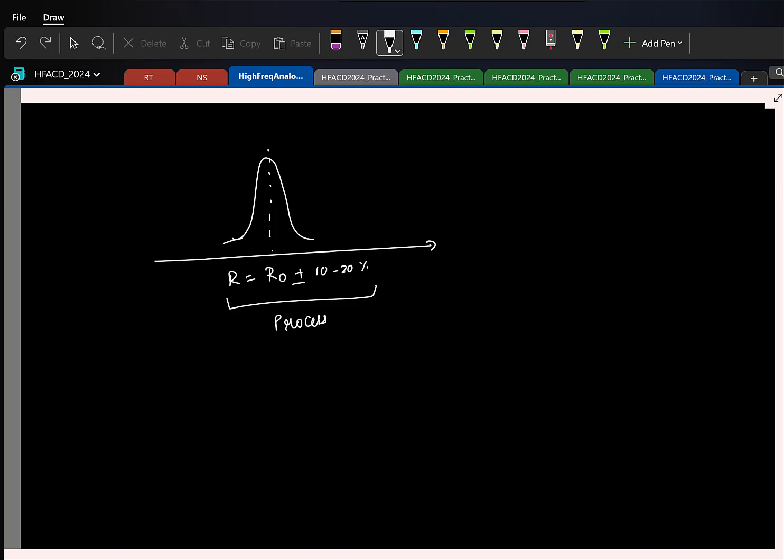On top of it, within a particular chip you will have variation in the component values. So if I call the actual resistance value, this will be the mean plus delta R. R is the mean value. Around the mean you will have variations, and this variation is due to the random mismatch. So here I plotted the distribution of the total resistance R. I will call it say R total. This contains the mean plus the delta R.